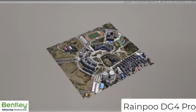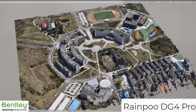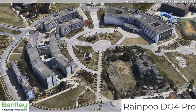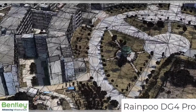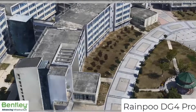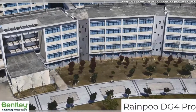But they shoot 5 photos each time: 1 down, 1 left, 1 right, and 1 forward and backward. They're flying, you see, 117 meters high. I wrote it down. And there's a GSD, ground sample distance, of 1 centimeter. This is a camera system that we see a lot of use in China. They're flying up and down, and in China it's quite normal that they fly in a city multiple times per day. And yeah, you see the results.